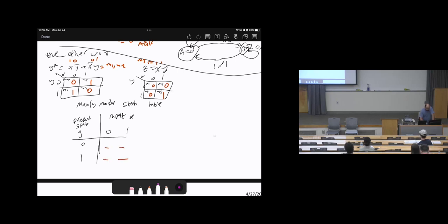So we have 4 squares. Copy these squares here. So we will copy the first sets. It will be 0, 1, 1, 0. Then we will put slash for the outputs. After that, copy this here. Then we will put here zeros, 0, 1. This is the textbook method. Okay? Then just put K-maps inside this diagram, then it will be easier like this one. So whatever you like, you can choose. Then from this Mealy model state table, you can convert it to the generalized table, or you can keep it as is. Either way is fine. So you have the tools, you have the options, so it's up to you.